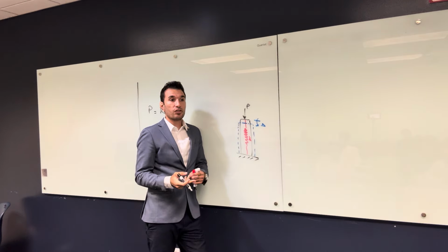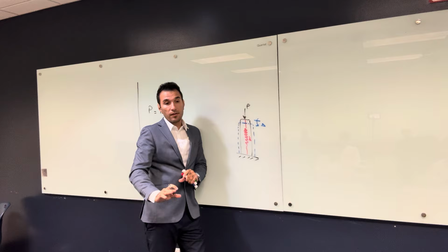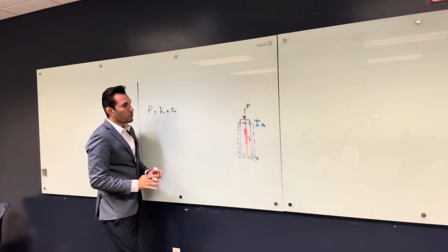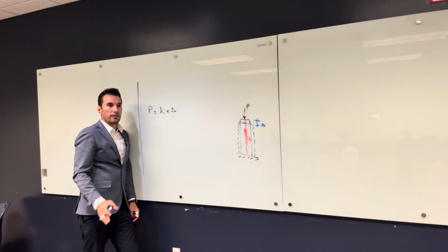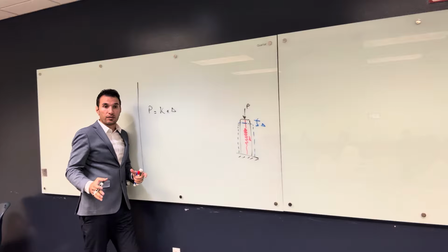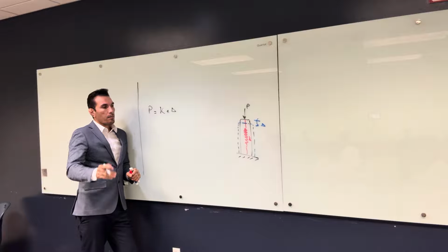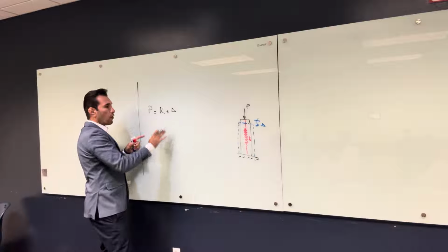Axial stiffness, shear stiffness, flexural stiffness, all these things. But the thing is, sometimes when it comes to a bigger structure, it is not only one K. The K, the stiffness of the structure, is not a single number, it's going to be a matrix. And we're going to see how we can convert this into a matrix. But let's think about how we can reform this shape.